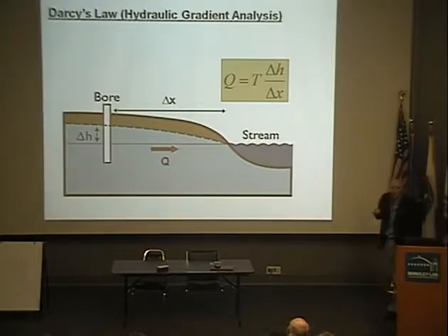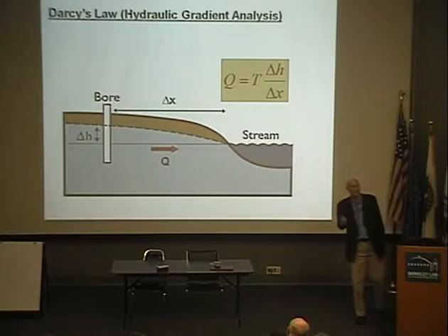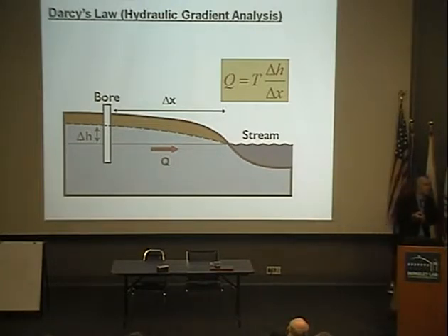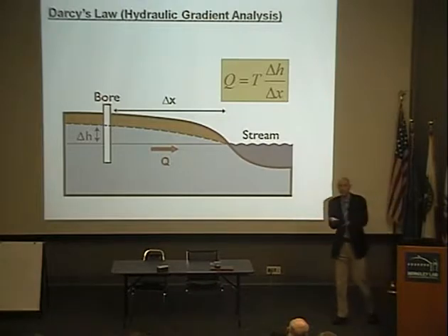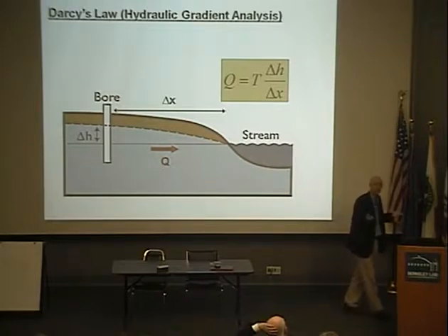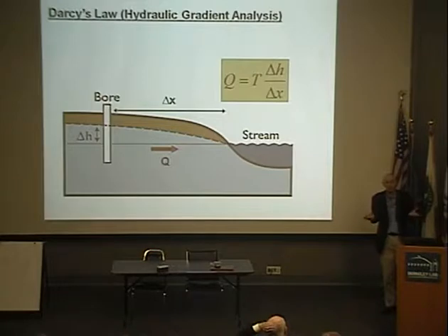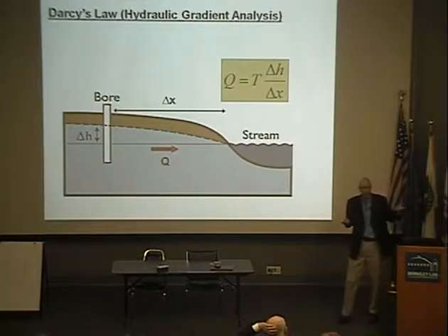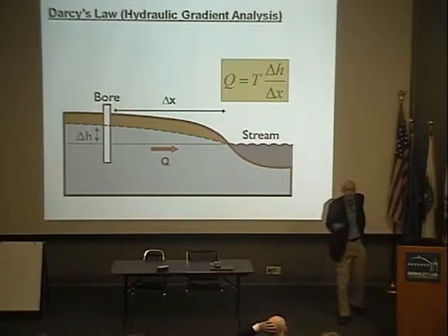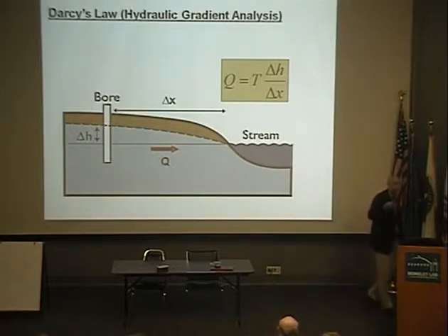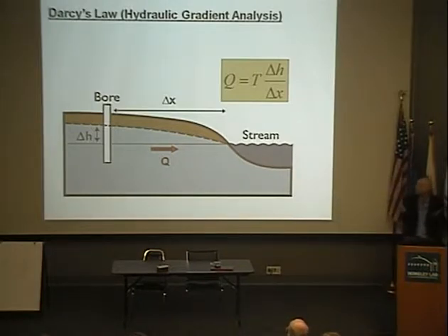Now, it's interesting here, not only have surface water and groundwater been managed separately for the last 100 years or so, and certainly in Australia, they were usually in different government departments responsible for managing those two resources, they devised completely independent monitoring networks. I'd be surprised if it's different here, but we have very extensive surface water gauging station networks, and similarly very extensive groundwater monitoring networks. But has anyone thought about putting groundwater bores next to surface water gauging stations to measure the exchange flux? There's actually very limited data where we're able to do this.